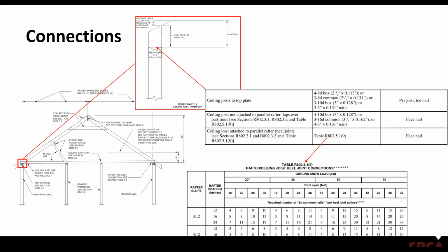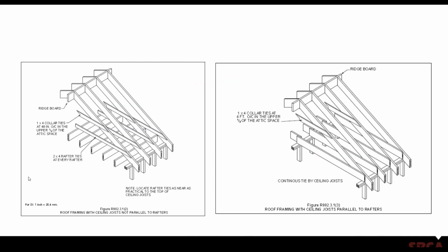Anyway, in the figure on the right-hand side, they're field building a truss, okay? In this case, it has no webs in it, but you've got the rafters that are forming kind of like the top chord. They're in compression and resisting the gravity loads and bending.